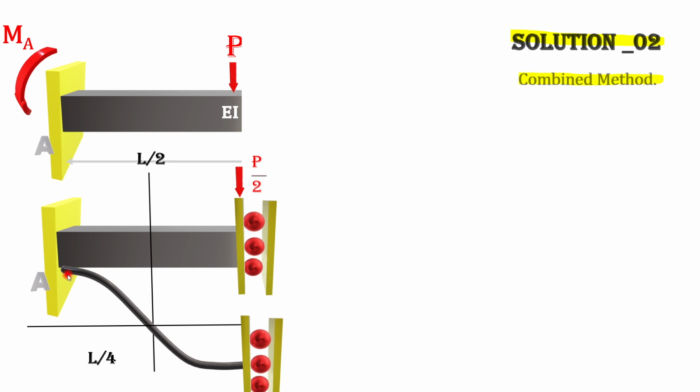As you can see here, the beam deflects like what you can see here, and we do know that the moment is also zero. We'll talk about it in next videos about what happens to a symmetric loading at the intersection of the beam with the symmetrical axis. So if M is 0, and you can easily see half of delta is here and the other half is on the other part. So if we call this part delta over 2, and because M is zero here, we can shift this force to the quarter of L.